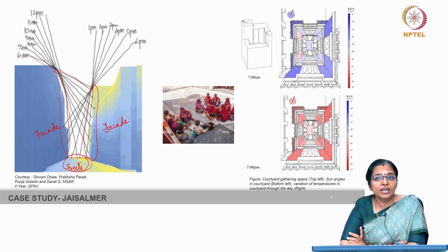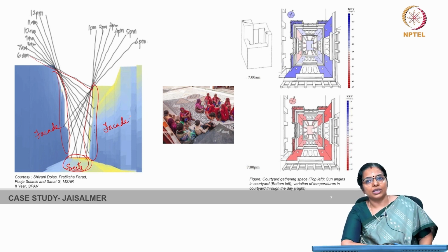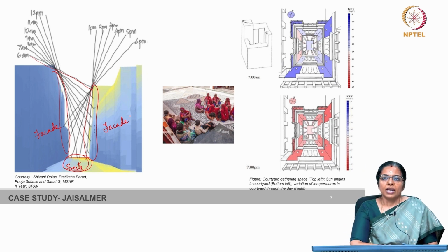Controlling solar penetration through orientation and projections is crucial in summer. It is optimal for a major east-west street orientation to have solar exposure on the street from 9 am to 2 pm, with a corresponding solar altitude ranging from 54 to 86 degrees.